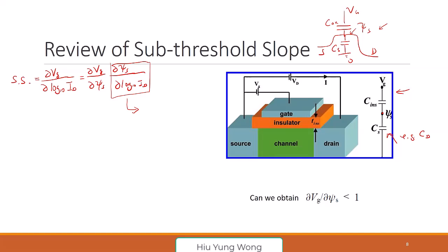Why do you say 1? That is the main point. To get a better subthreshold slope, that's why I said 1, so that it will get the full 60 millivolts per decade. Exactly. So the value is actually 60 millivolt per decade. What you mean 1 is 60 millivolt per decade. Or it is kT over q natural log 10. This is this part.